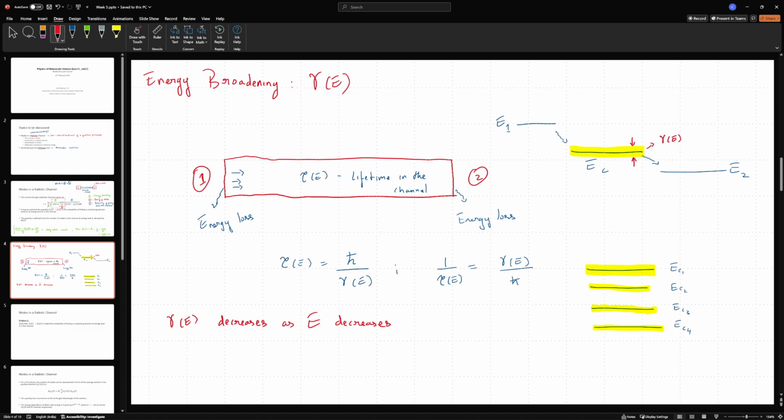Now, what do I mean by modes? Remember that while in the channel, the electron cannot gain or lose energy because the transport is ballistic, which implies the electron cannot move from one energy level to another. Therefore, when we are inside the channel, only those energy levels will be chosen whose broadening does not cross over into another energy level.